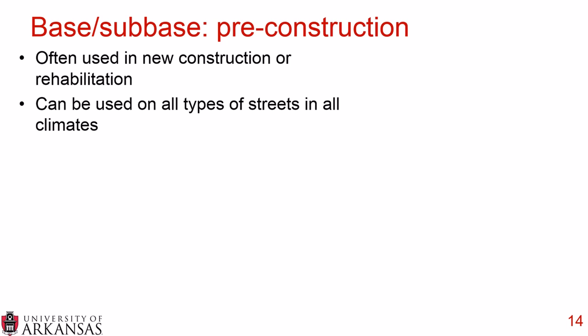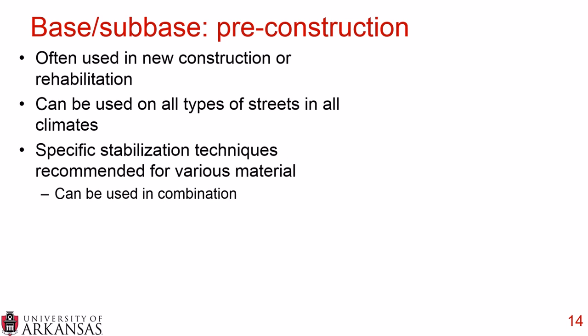Now we're thinking about pre-construction considerations. Base and subbase stabilization is often used in either new construction or complete rehabilitation. It can be used in all types of streets and in all climates, so it's very versatile.